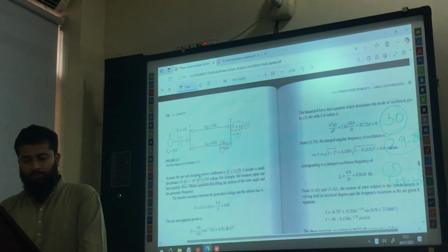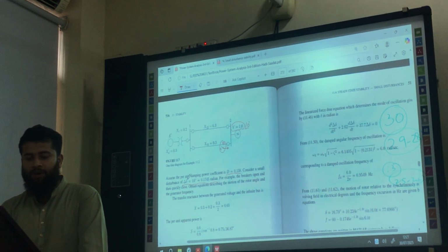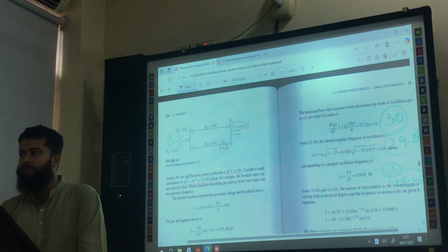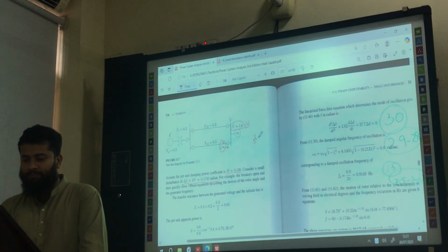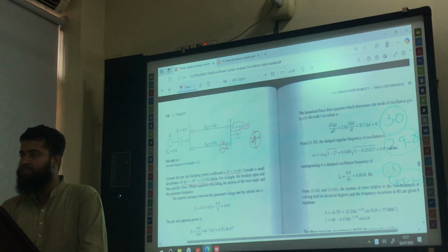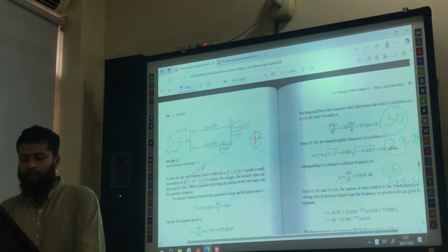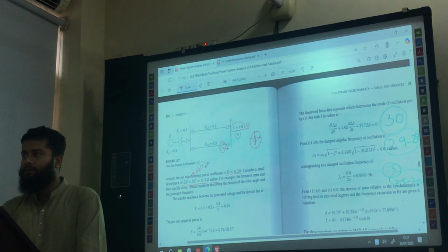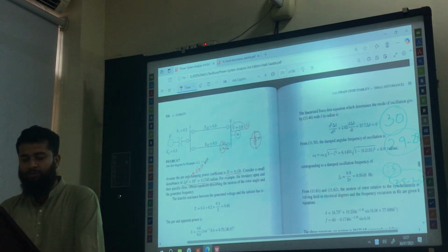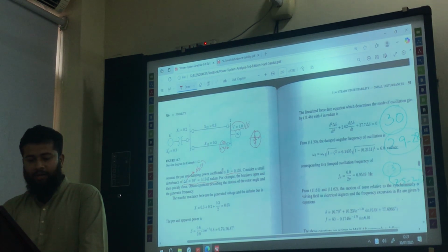Okay, you have to consider this thing. Whenever this information is given, that the disturbance is given as del delta, that means this is actually the unforced response, right? Because you cannot see any del Pm term here. That means there is no forcing function. So how will the system go to the disturbance state? Using this initial condition, the del delta, right? So this is actually our del delta of 0, and our del delta of 0 should be non-zero to convert this system into the disturbance regime. For example, the breakers open and then quickly close.